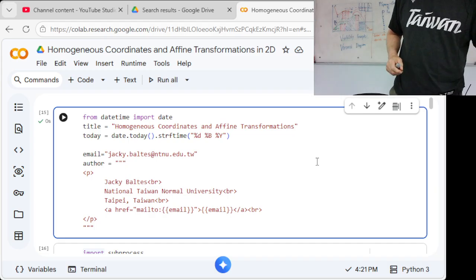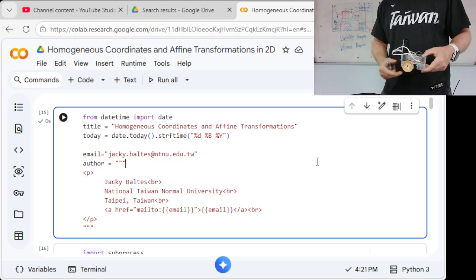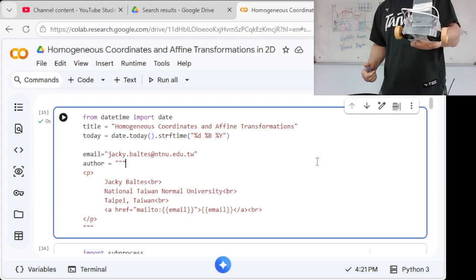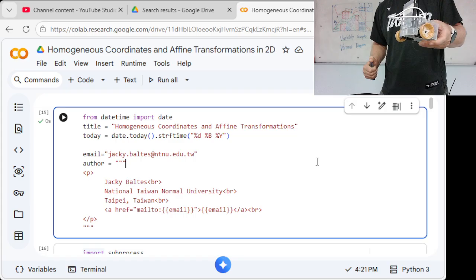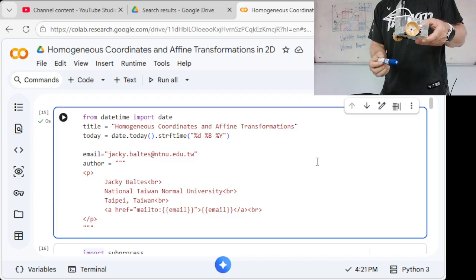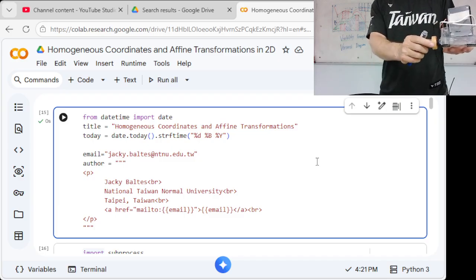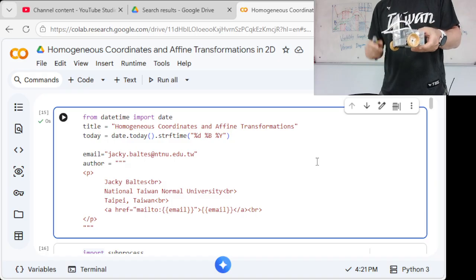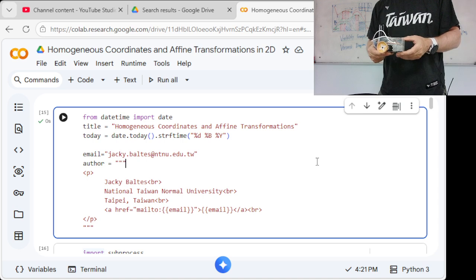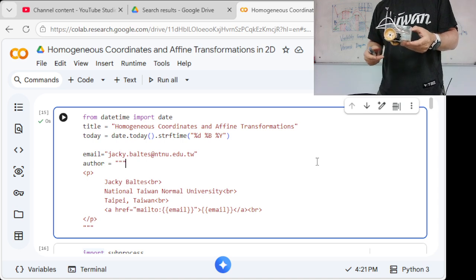Now, I actually like to build my own robot, so my students and I build our own Turtlebot robot using, let's say, recycled materials, frugal recycled materials. So we actually use two RC servos, the caps from the milk bottles, a USB battery, and a Raspberry Pi Pico 2 as the brain of the robot, the controller of the robot.